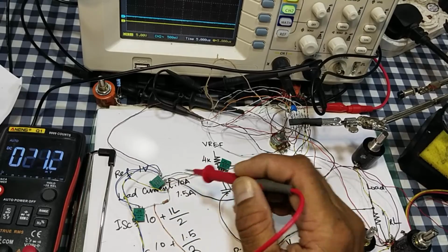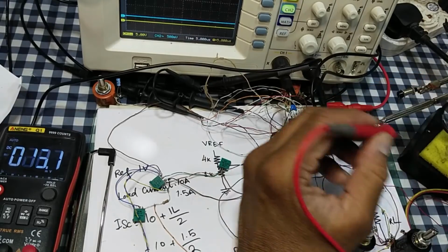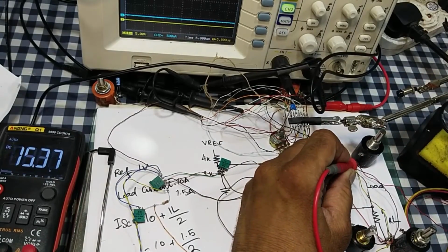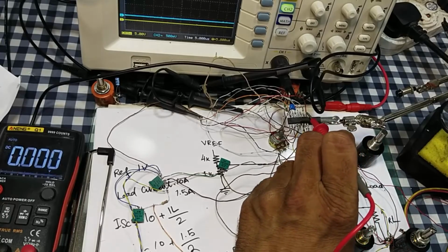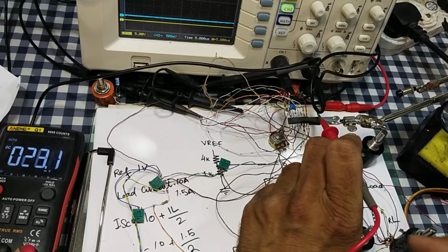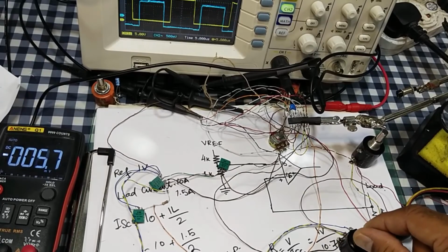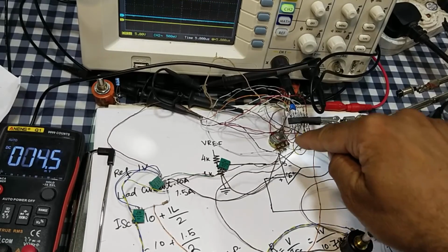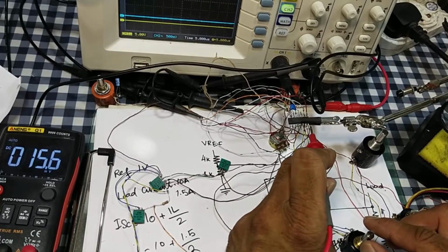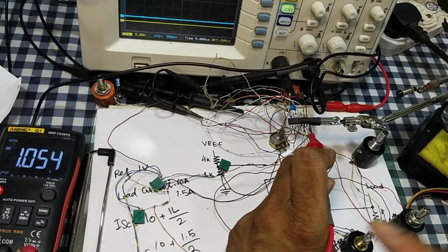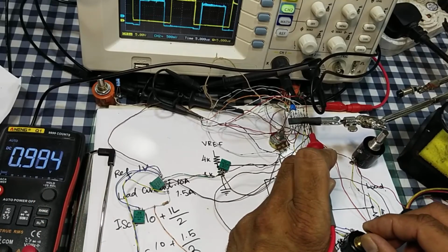It is programmed at 2.5 volts, and when there is 15 volts in the output, 15.36 volt, this IC will find 2.4 volts, and if there is a short circuit, this IC will cut off the command. Why? Because the feedback at pin number 16 is now 1 volt. So this IC will go in protection mode.